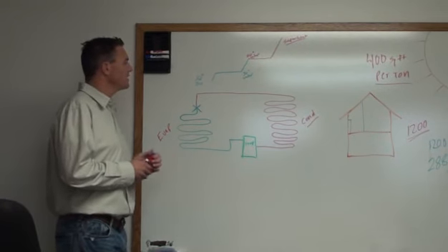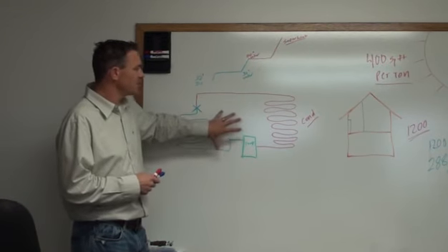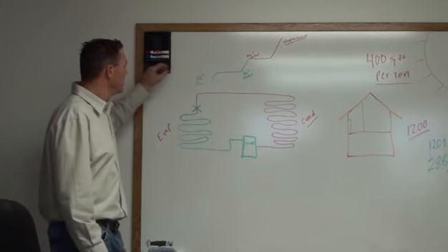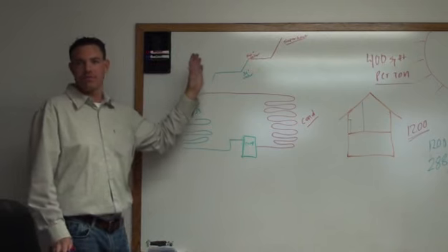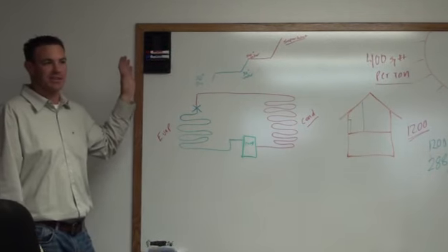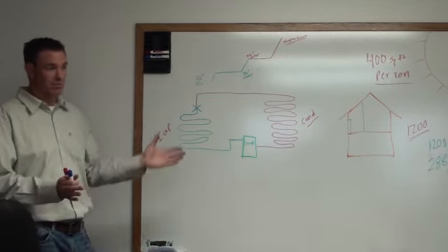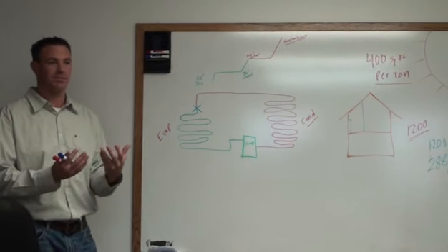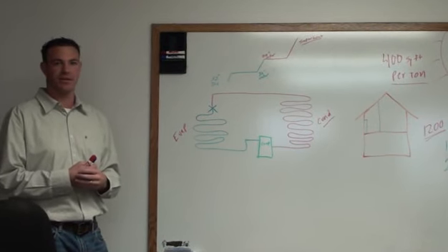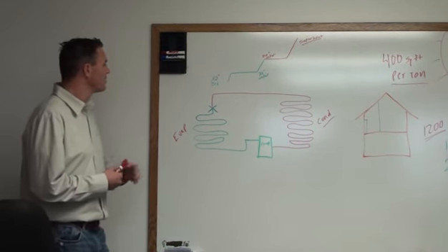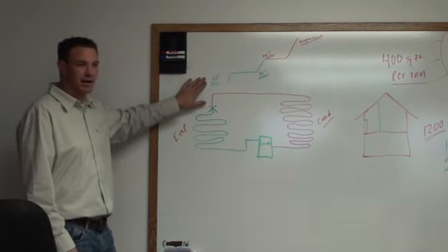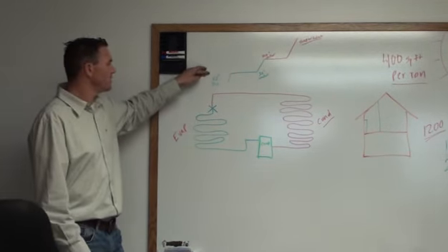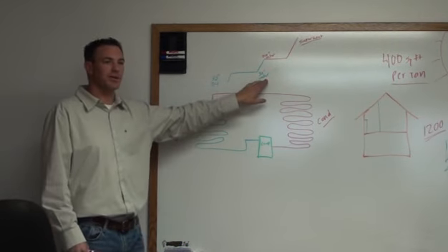So to kind of give you guys an idea of what happens in the air conditioning system, we're going to use water. On a scale, everything above 460 degrees below zero essentially is heat. Okay, so if you have a block of ice that's 460 degrees below zero, everything that we add to that block of ice above and beyond there is going to be additional heat. So if you were to take a 32-degree block of ice, we're going to add X amount of BTUs and bring that 32-degree block of ice to 32-degree water.